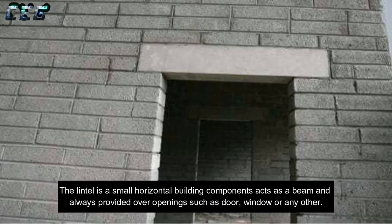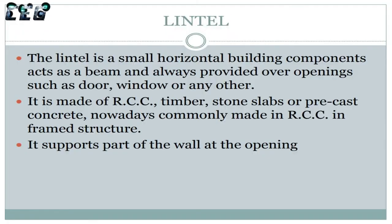Lintel. The lintel is a small horizontal building component that acts as a beam, and is always provided over openings such as a door, window or any other. It is made of RCC, timber, stone slabs or precast concrete. Nowadays it is commonly made in RCC. In a framed structure, it supports part of the wall at the opening.